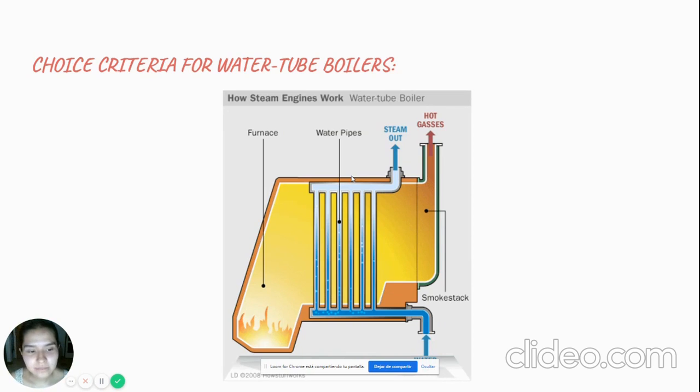They are not recommended when the impurities in the gases are very abundant due to the difficulty of blowing. Fewer mechanical failures occur in them than in fire tubes. It is possible to boil them with natural circulation and with forced circulation. Certain water tube designs can be built with a superheater, air heater and economizer.